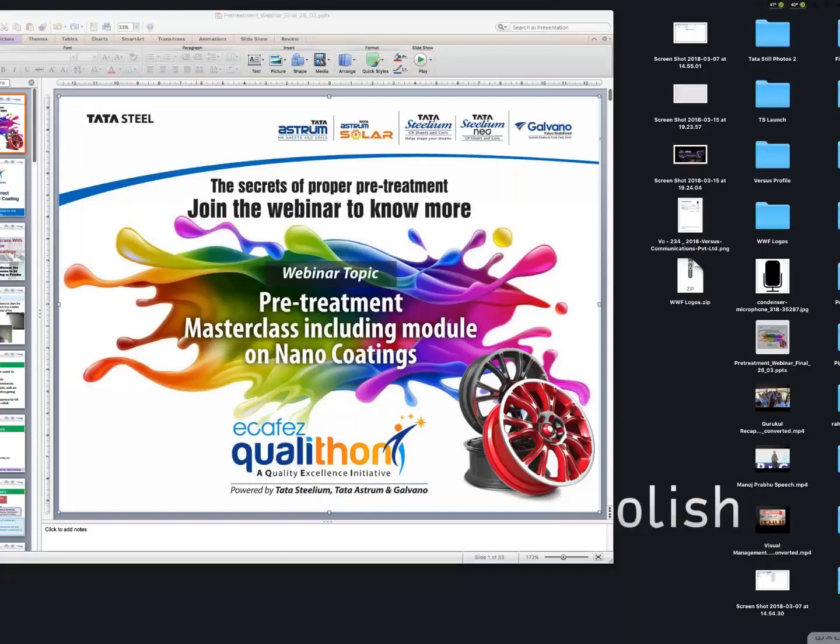Mr. Digambar Sapre is asking how to clean the welding surrounding areas. Now, welding surrounding areas, basically, number one is the black parts which are developed are mainly because of the oil which burns, and removing this burnt oil is difficult or impossible with this chemical treatment. So you have to ask your people to clean the oil before welding, at least the area which is adjoining that particular weld line.